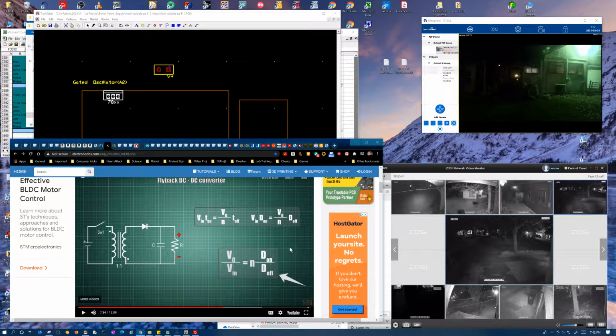Okay. That's interesting. So I assume N is the turns ratio here. So if these were equal, that would be 1, and so V out equals N times V in, but also times the duty cycle ratio, so you can actually change the voltage by changing this ratio here.